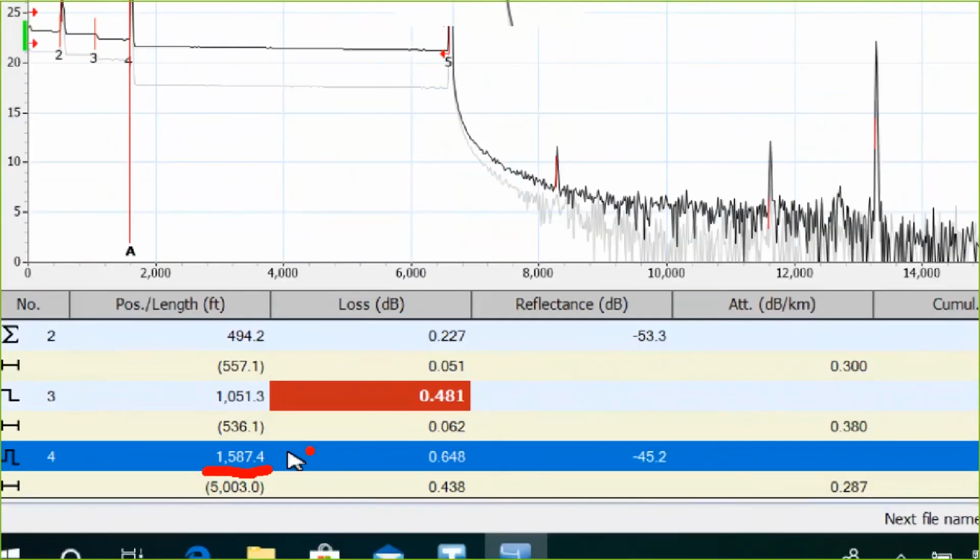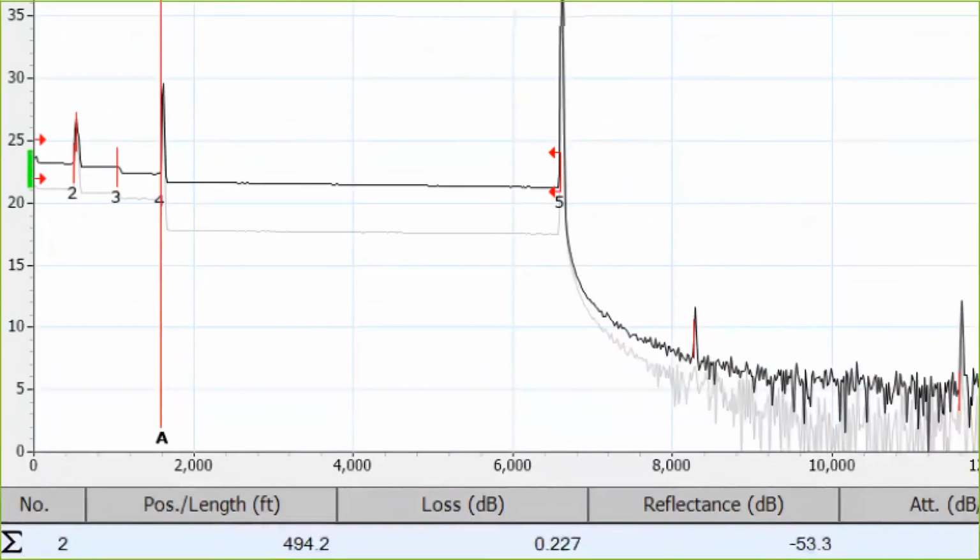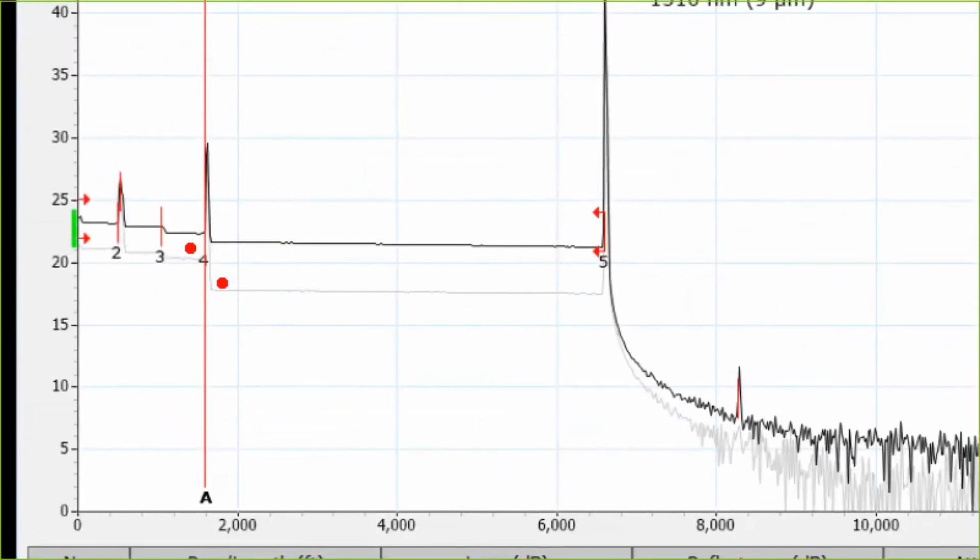And if your prints have the sheath footages for your OSP cable, so when I was a splicer, we would write down the sequentials on the cable. If you have a critical span with a critical customer that has SLAs, like governmental work or 911, you can go to one of these spans. Let's say we had a splice here and a splice here. I could access both of these splices physically, crawl into this hole, and read the sequentials, the numbers on the cable sheath. It'll give me a number here, and a number here.